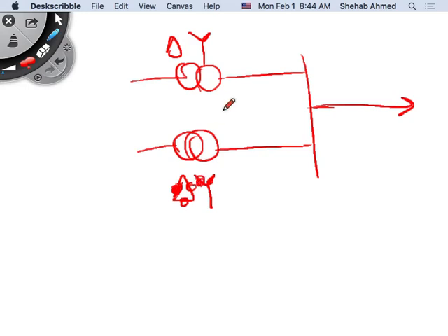Because if you do that, you may end up with a star here and a star here, but maybe the star here is shifted with the voltage here, across the line to line, versus the voltage here across the line to line. This is 0 degrees and then this is 30 degrees. Can you do that? You cannot. Instantaneously there are 2 different voltages. You will have currents flowing between them, right? So it's not how you would do it.